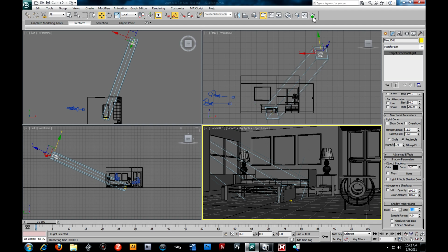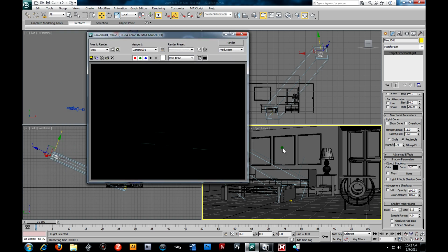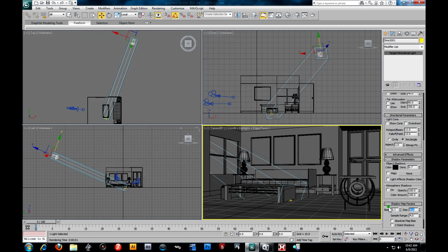So when I render that out, our shadows, like I said, you can't really see them right here, but as we start placing some fill lights, we're getting low quality shadows. So I'm gonna raise that up to about, let's go 2048. So you usually multiply by 2. 512 by 2 is what, 1024, and then 1024 by 2 is 2048. And I've heard of some cases people going 2048 times 2, which would be 40, I forgot, 96 or something like that.